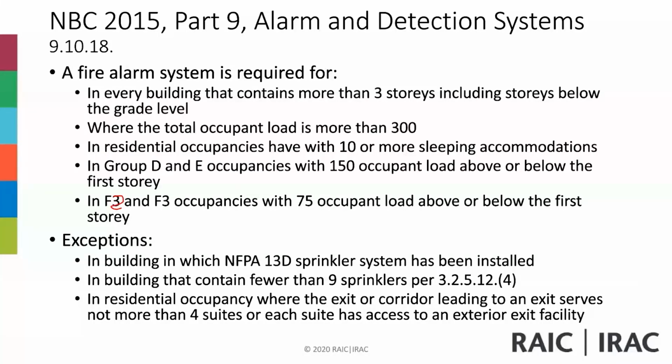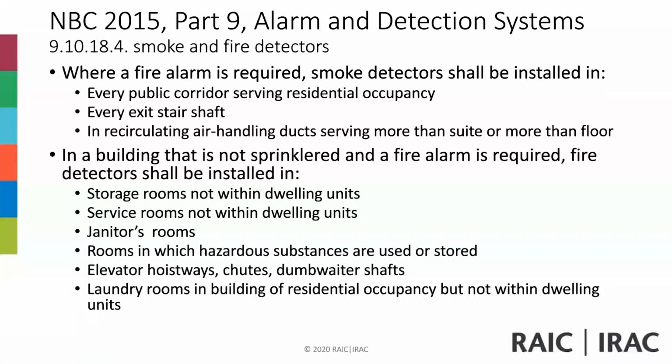Okay, no question. Where a fire alarm is required, so I'm looking at 9.10.18.4, smoke detectors shall be installed in every public corridor serving residential occupancy, every exit stair shaft, and recirculating air handling ducts serving more than one suite and more than one floor.